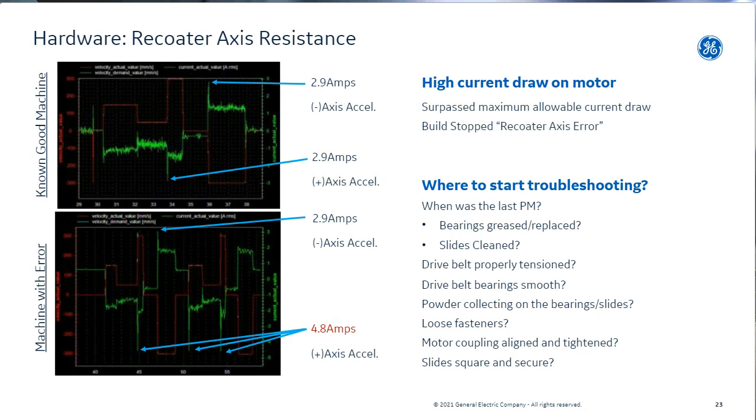and then flies backwards to the side where it rests during the scanning. Huge spikes when it's moving to the left on this lower graph here. And so they're basically killing the build because the torque is too high on this motor. So you quickly dive into these: where can I start fixing these bearings and what's going on here?